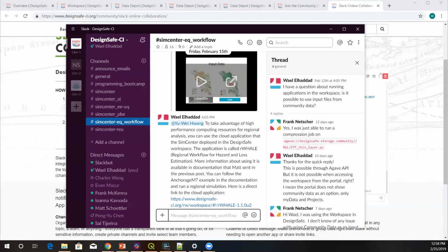Other differences might be in the methodology used for losses. For instance, it's FEMA P58 compared to HAZUS. So you have to auto-populate your building model with components, and you have to start creating realizations for different quantities of these components in the building. And it's a more detailed process to calculate the losses.